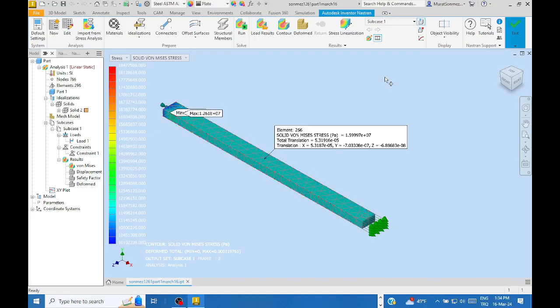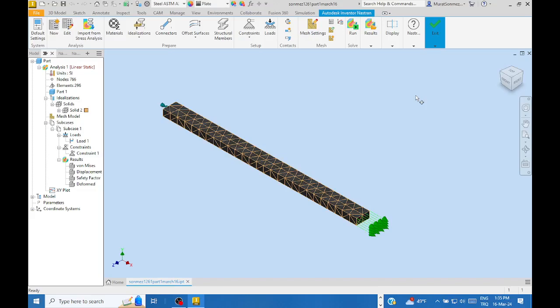Yes, you can see the simulation like this. It is possible. If you want to see the actual deformation, by the way, if you turn back to the boundary condition environment, you need to have a look one more time at the results of the calculations. Bring the cursor to the browser, on von Mises, or displacement, or factor of safety, whichever is the case. Right click the mouse.